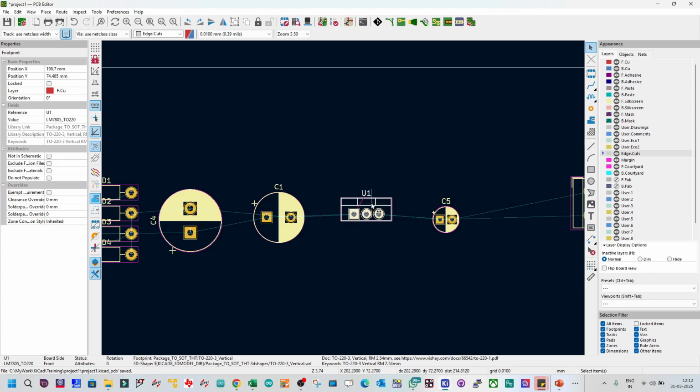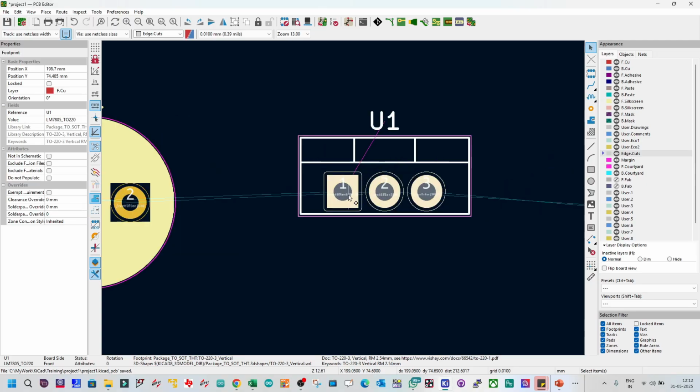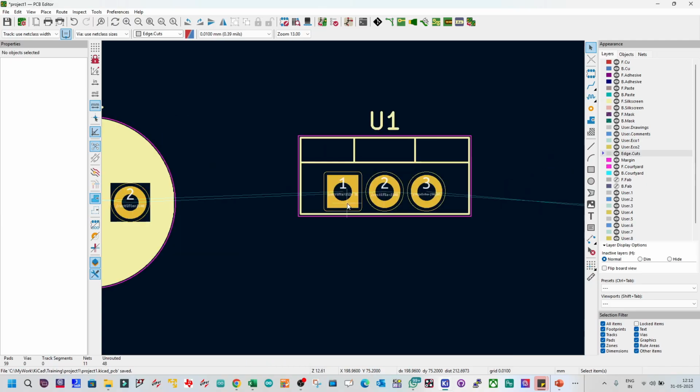From all the angles you have to think, like how much current is going to flow in this pin. These are all technical things, electrical understanding, that one layout engineer must have. I'm not saying he should be an expert, but he should have at least a basic understanding of how much current will enter, so that he can decide how thick a trace we have to place.